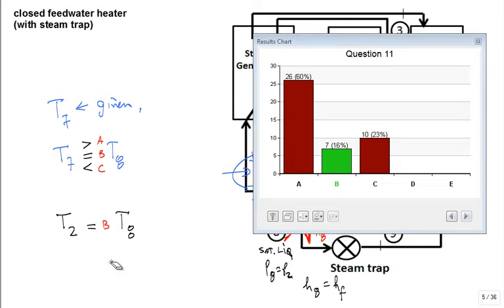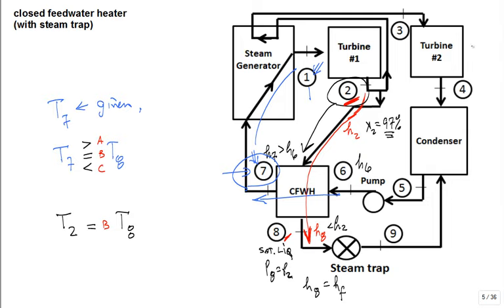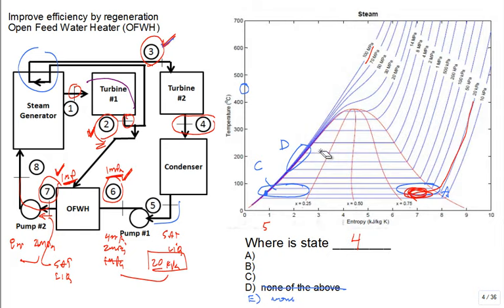And now we go and we will drop back. Maybe a diagram will help us. Here is a temperature entropy diagram. I know that I'm changing it up, but let's say that was a 1 megapascal pressure line. True? I want to sketch it. Notice right there. And how am I sketching this line in the dome? It's a straight line. Does the temperature change at all? Nope. And if you remember, that was around 295 degrees C, the saturation temperature of steam at 1 megapascal.